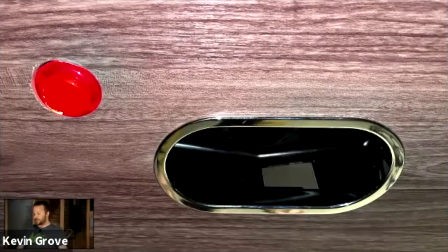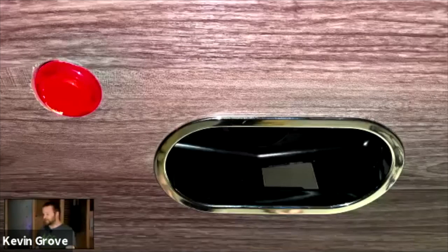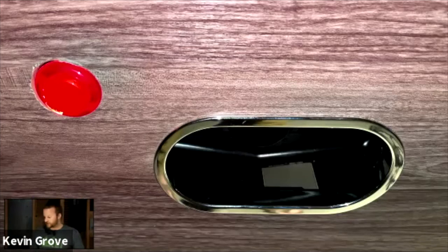Oh, and sorry, the ball retrieval. So this is the LED button that is on each side of the foosball table that each player would press in order to commence gameplay. And the 406 is in there as the ball retrieval. As the ball hits that sensor, for example, in the timed halves mode, the clock starts back up. If it doesn't sense that, the backup would be just hitting the button to restart the clock.